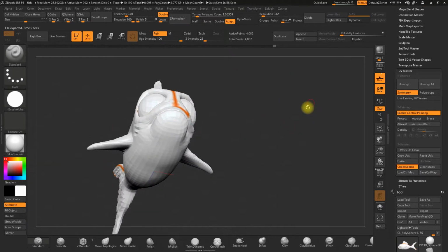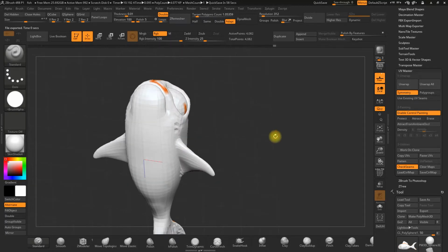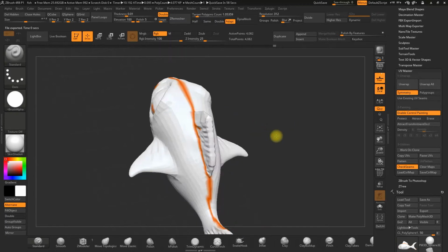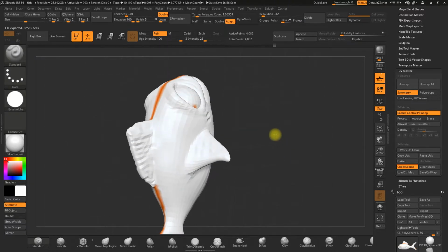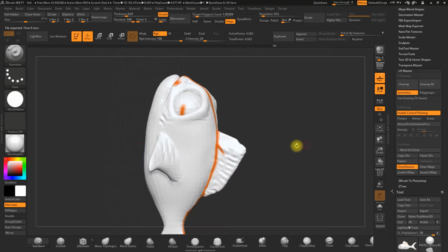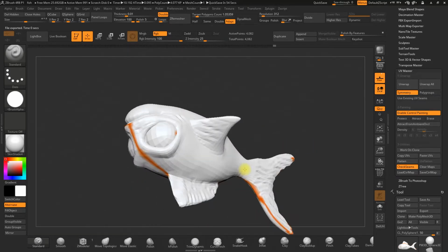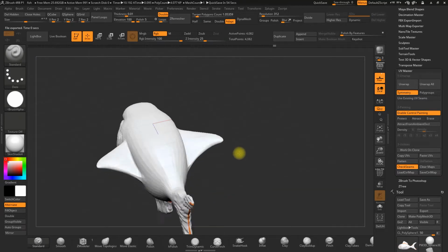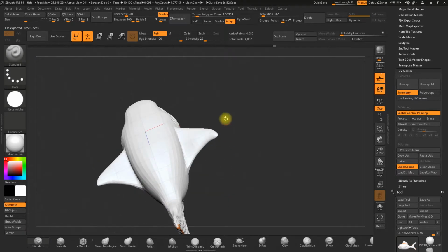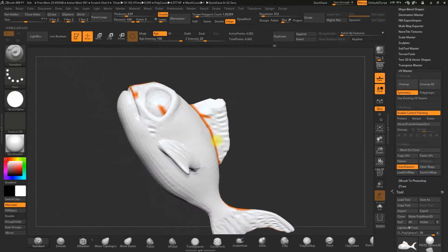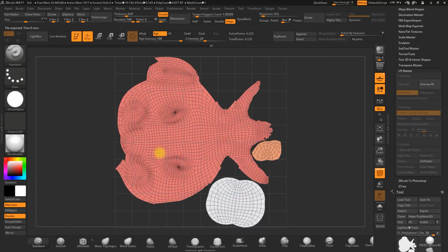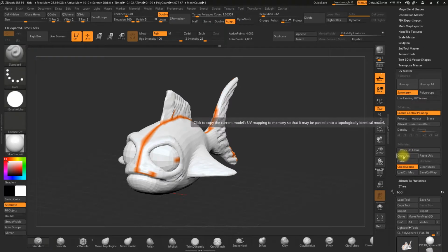The fins weren't cut, and on the bottom of the model, there wasn't a cut either, because when the texture unflattens, it is not necessary. As the eyes are separate because we merged the objects but didn't apply a Dynamesh, we can see the cut is made towards inside. So don't worry, because it's all good. ZBrush is not the best program to do this, but for the animation we want to do afterwards, it's more than enough. After we unflatten the texture, we click on Copy UVs.